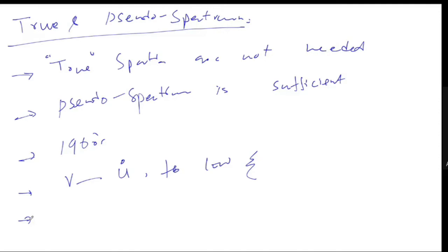Today we consider the pseudo velocity spectrum the preferred spectrum because it directly provides the peak deformation and the base shear force acting on the structure.